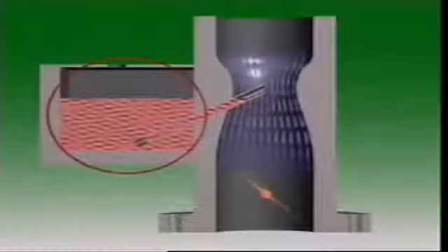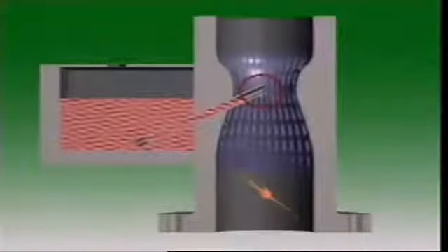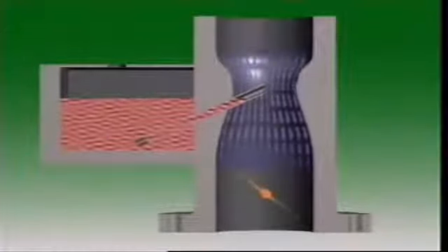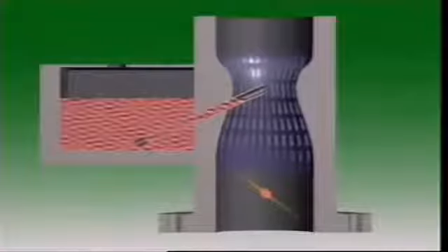This downdraft carburetor has a float bowl for fuel. One end of a tube is immersed in the fuel. The other end is a fuel discharge nozzle in the venturi. As the piston moves through intake, it makes a low-pressure area, and as a result, air from the atmosphere flows through the venturi. The venturi here is narrower than the rest of the barrel, and it is shaped to make the air speed up as it passes through.